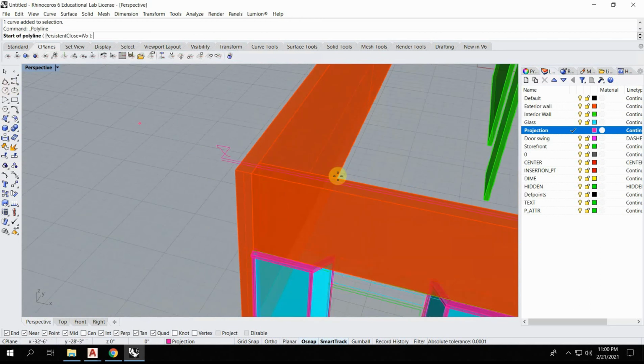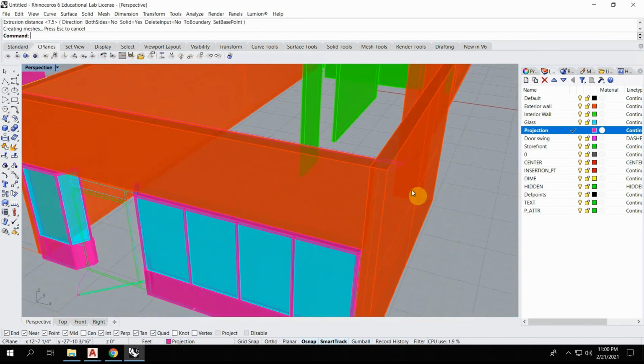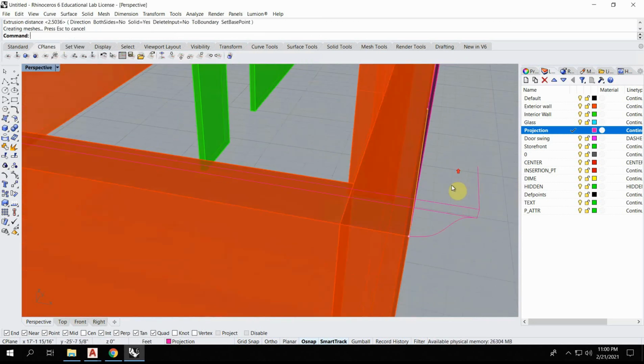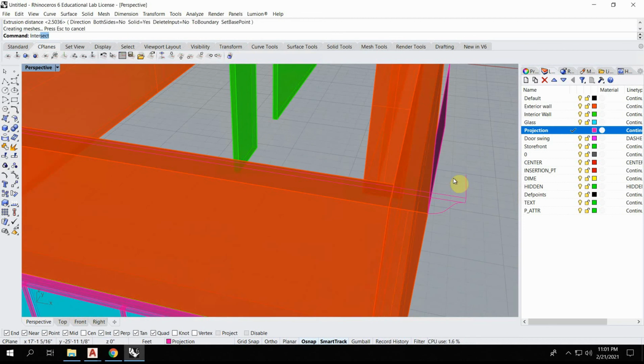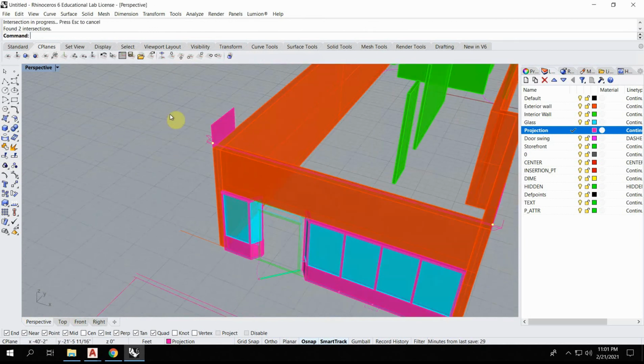So I'm going to make a construction plane to help me do that. So I'm going to select this, hit extrude, curve. And this is geometry I'll delete later. I'm just putting it here so that I can find where the intersection is. Extrude, curve. I can't type today. Okay. And I'm bringing that up. I'm just going to intersect that with our rail. So intersect, select our rail, select this object, select that object, hit enter.